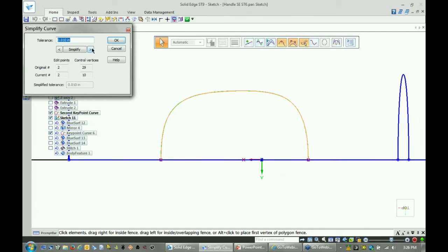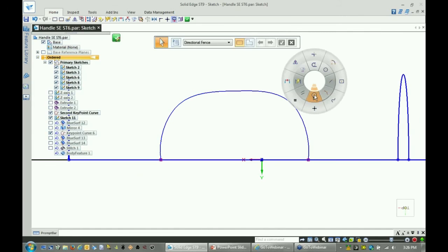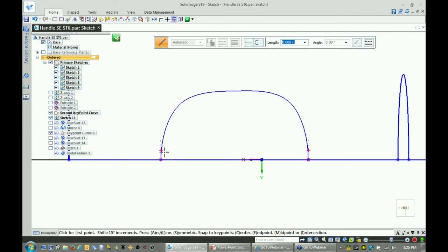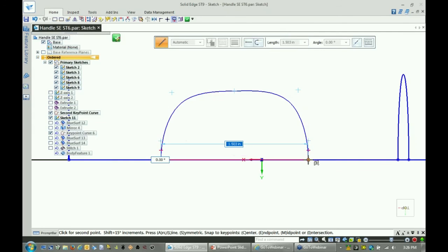We can simplify that curve just by adjusting the tolerance, chordal tolerance. We can adjust how simple or how complex that curve is, and then we can simply adjust this curve by applying constraints like we normally do with 2D geometry. Let's say polygon controlling points for people who are familiar with curves. That's typical. Let's add an additional line here to connect these 2 points.